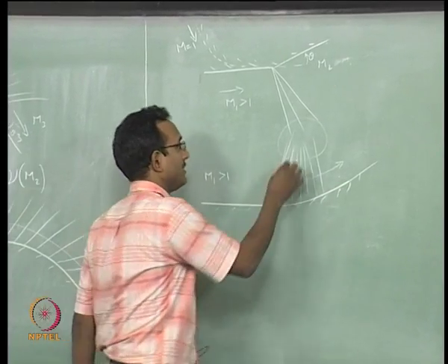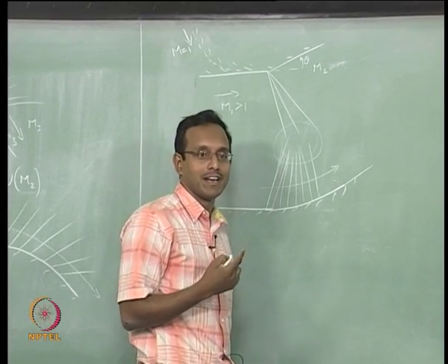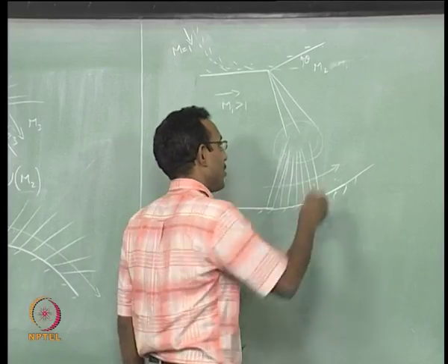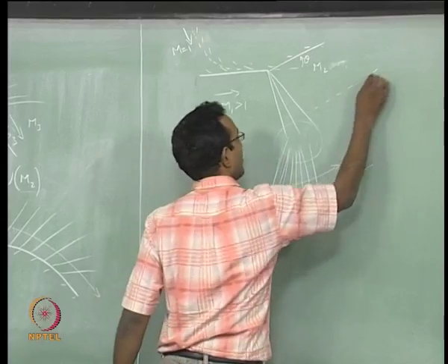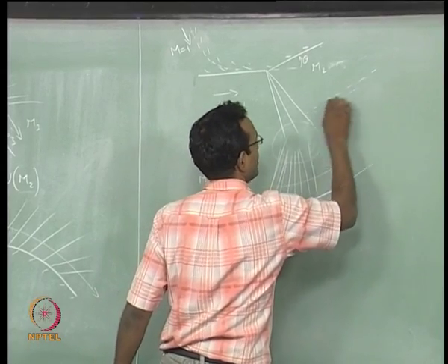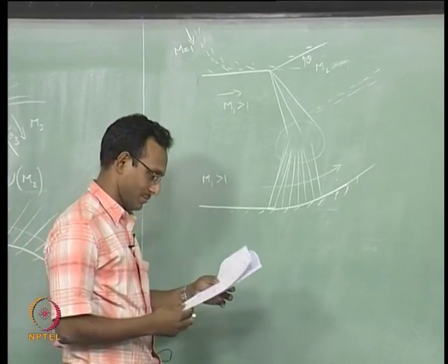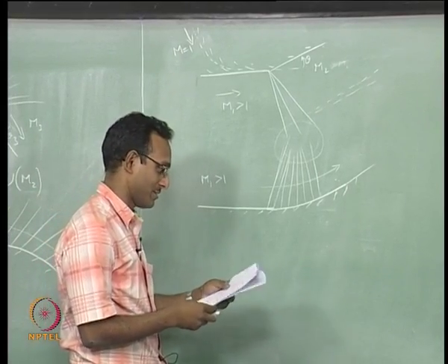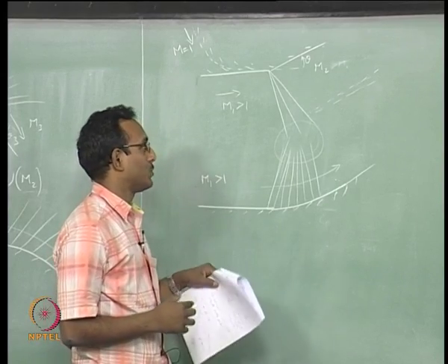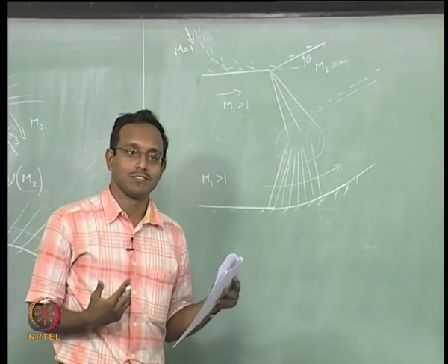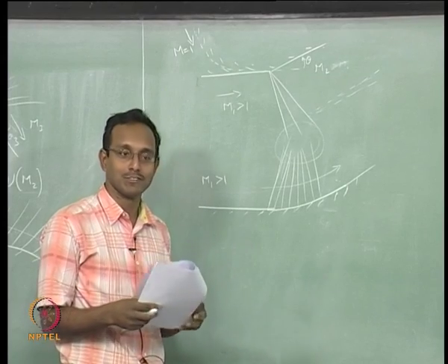But when these things interact, similar to what we did last time, when oblique shocks come and interact, they may form a slipstream kind of stuff. Here also there will be some slipstream forming here. Not just one slipstream, probably a whole bunch of slip regions might be formed out there. We will just ignore all that for now. I will show you pictures of that if needed. And so with this, I can now start solving problems. Like I can just tell what will be the Mach number, I can start predicting Mach number values.